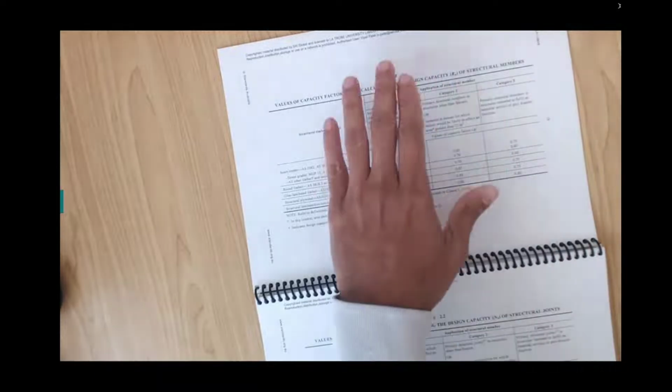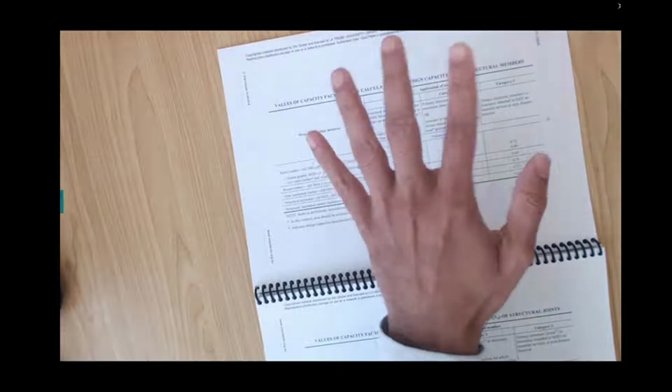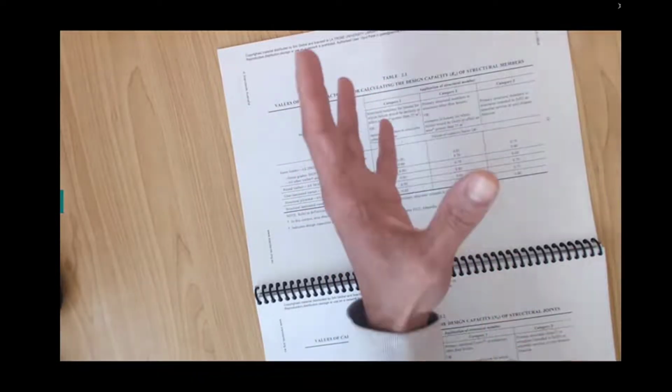Now in these tables you have category 1, category 2, category 3. I will revise it again. I have done this one multiple times. Probably this is the 4th time that I'm revising it. Category 1 is where your member is not a primary member, it is a secondary member. Meaning when it goes into service and if it fails, then not more than 25 square meters of area will be affected, or the users in that area. So basically they're saying that your users will not be affected much if you are in this category. There is less safety risk on category 1 members.